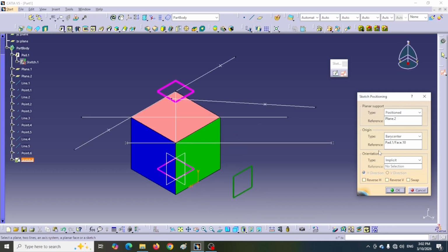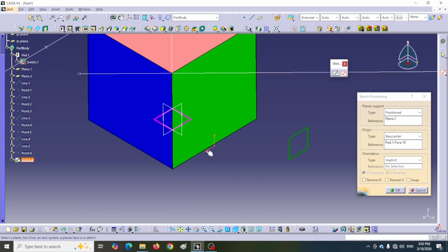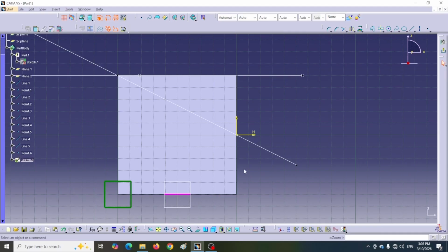The first section is called Orientation. In this section, we define the horizontal and vertical axes and their positive direction. When you enter the sketch environment, you have a horizontal axis and a vertical axis. These two axes have positive and negative directions. Note that here the two selected axes will be perpendicular to each other. If we want our axes to be non-orthogonal, we must use other methods like the coordinate system tool.